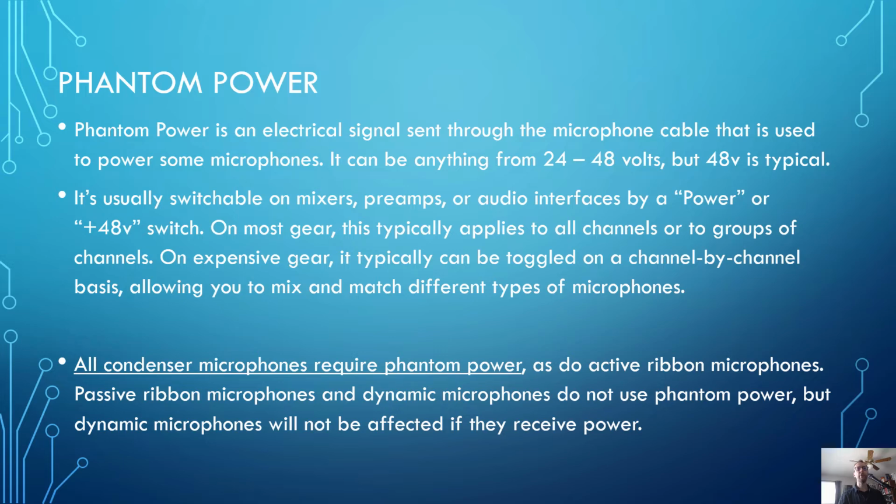All condenser microphones require phantom power to operate, as do active ribbon mics. Passive ribbon mics and dynamic mics do not use phantom power. Again, if you send phantom power to a passive ribbon mic, you may blow it up. Dynamic mics, however, will not be affected.